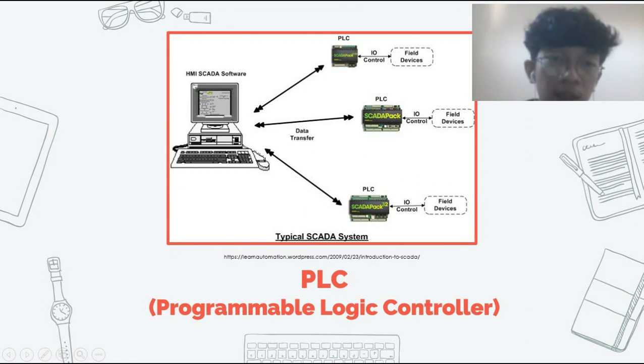And next, PLC. PLC, or Programmable Logic Controller, is a logic controller that can be programmed according to our needs. PLC in a SCADA system is usually placed on the RTU, so PLC is a subsystem of the RTU. This PLC is in charge of processing or retrieving data from the transducer or sensor transmitter, which also makes it possible to control the system at the RTU. For example, it is used for valve opening setting.